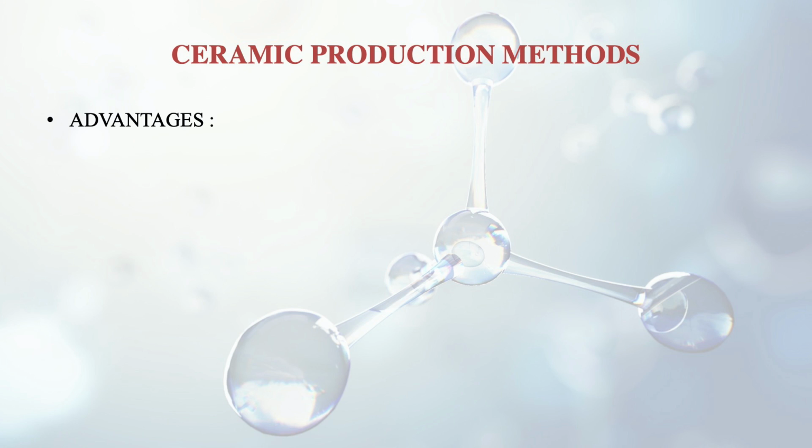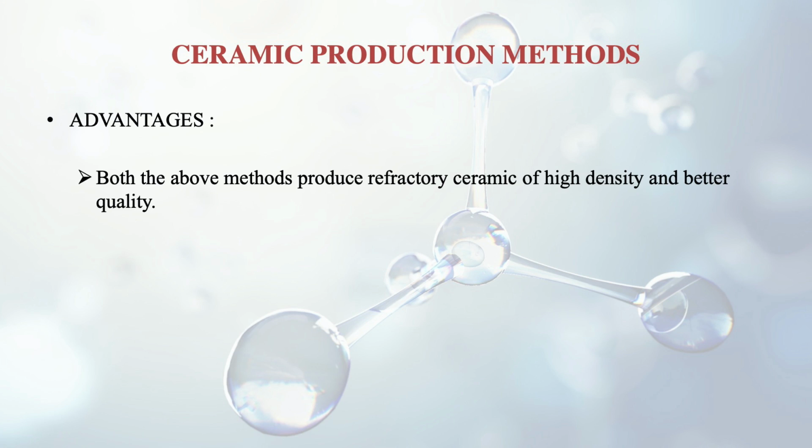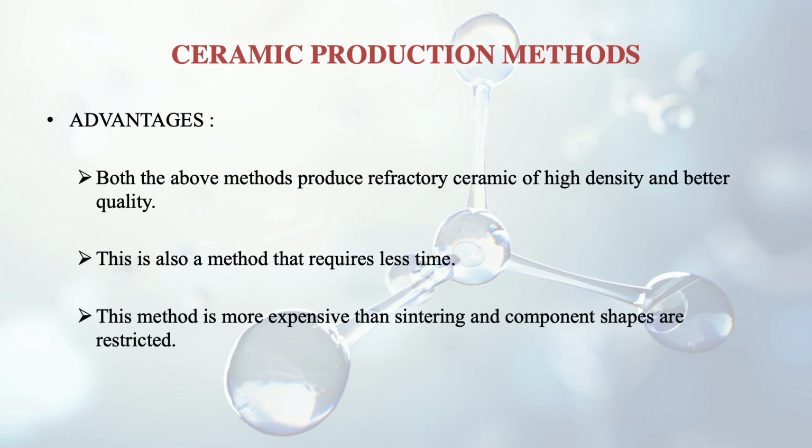So what are the advantages of this process? Both the above methods, meaning the hydrostatic pressure and the unidirectional pressure, produce refractory ceramic of high density and better quality. This is also a method that requires less time than the other methods. So this method obviously is giving us better results and requires less time, but it will be more expensive than sintering, and component shapes are also restricted.